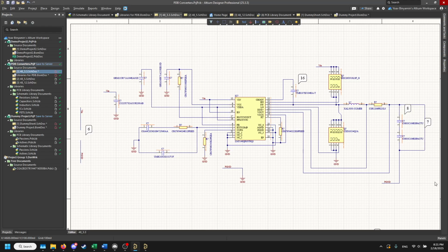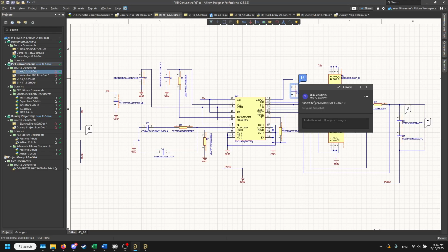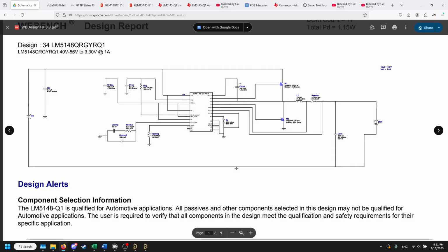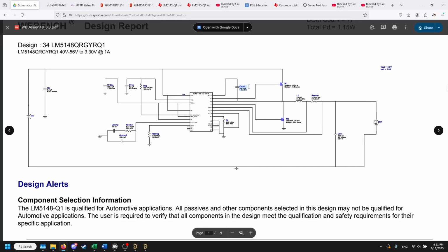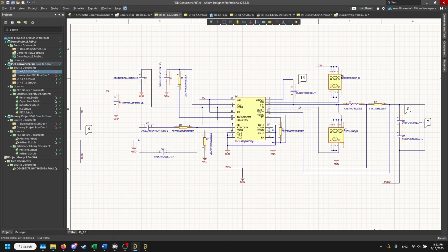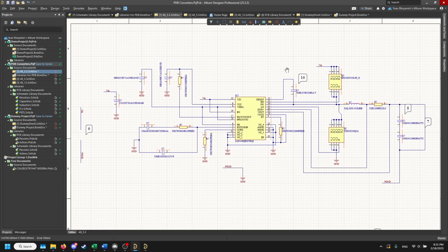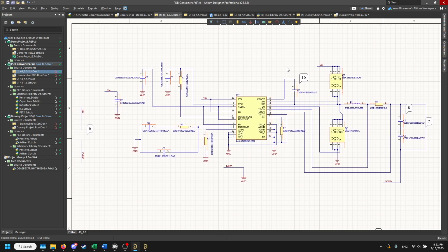And the final thing, I just have commented this, but it's a substitute. It's the correct part, but it's not the part that's listed because it was obsolete. So you might want to comment that for later, like if your design doesn't work and maybe it's related to the capacitance, then you can check that maybe your substitute didn't have the correct values.